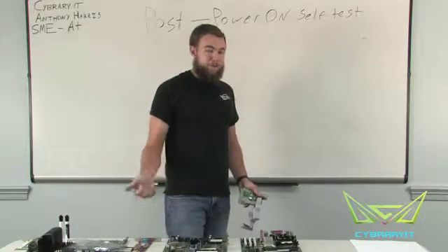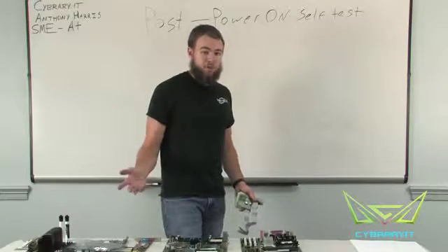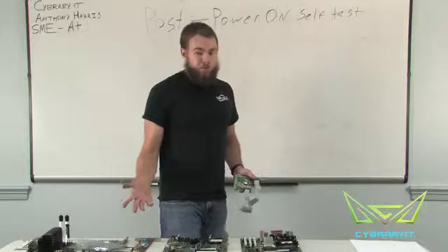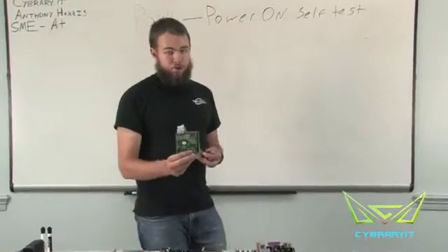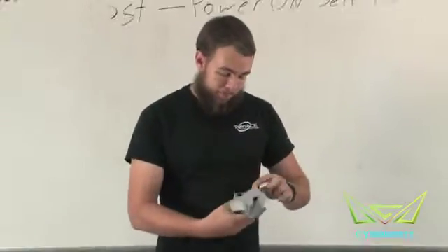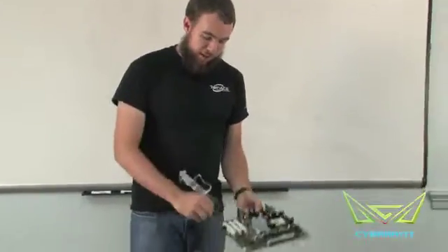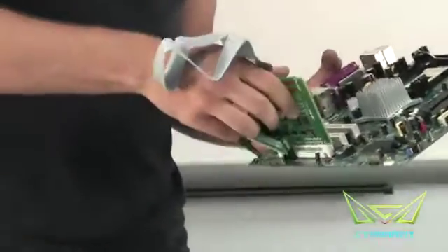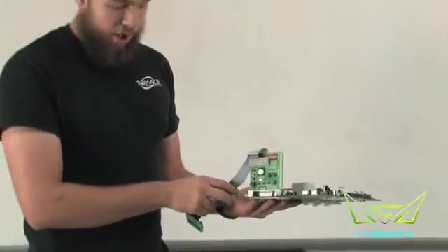So if beeps aren't really giving us anything and we don't have any error codes on the computer screen, well, there's a third option that we can go through, and that's called our POST card. Now, this isn't the type of postcard that you stick a stamp on and send through the mail, but rather a postcard that we can plug into our computer. We plug the postcard into one of our PCI slots. And this is done, of course, while our computer is still off.